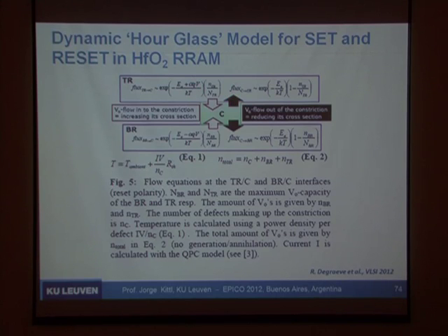And the dynamic balance is on one part the diffusion-like contribution, which is proportional to how many vacancies you have on one side or the other. And the other part was the field-driven part. Taking into account the quantum mechanical nature of the constriction, the field part doesn't act if you're inside the constriction. So all of these things are completely different from many of the models that were around for explaining this type of switching behavior. I think this is something to think about. I encourage everybody to also make criticisms, but I think there's something here that's on the right track.